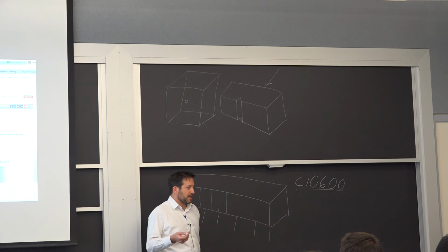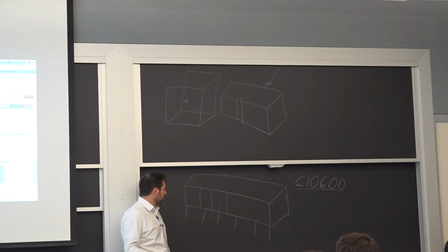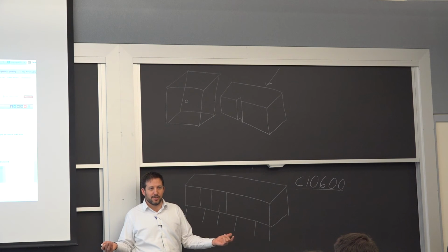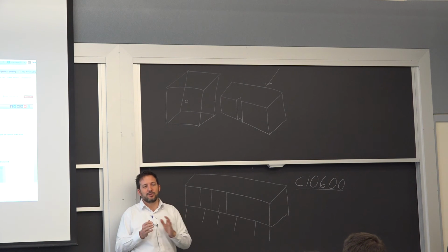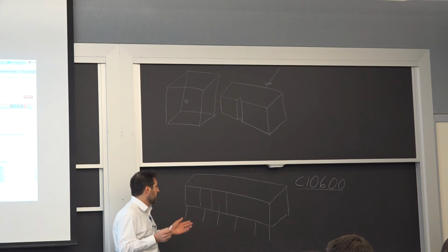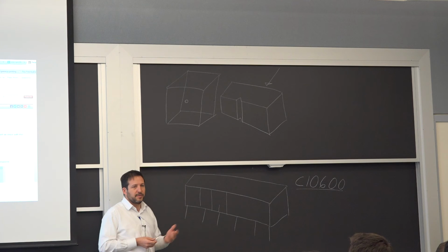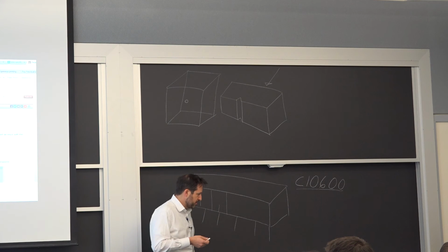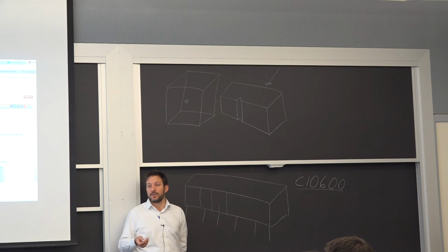Why is it happening here and it's not happening on a building? Well, the building is made out of steel. So one cycle per year, a little bit of expansion, a little bit of contraction, the welds will take it. They'll deform. You don't really see it, but they'll stretch and accommodate small variations very easily. We're not talking about a lot of cycles here. If you have 50 years, 50 times, not a problem. When we're talking about fatigue for steel, we typically are talking about thousands of cycles that become a problem for initiating cracks. That's really what we think about.